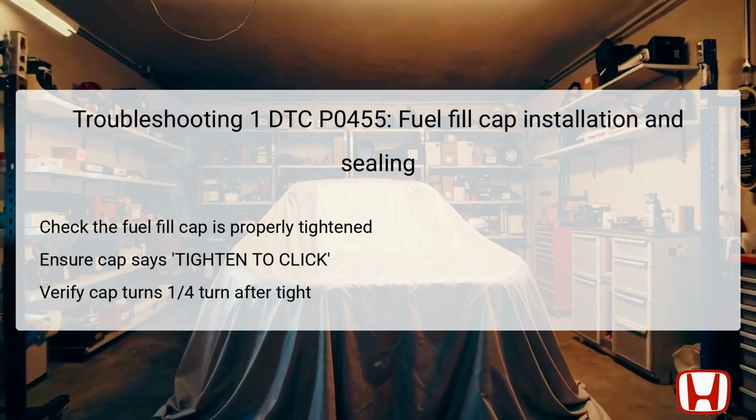A loose or improperly installed fill cap can cause the vehicle's diagnostic system to detect a large leak due to vapors escaping from the fuel system. If the cap is not tightened correctly or is damaged, replacing or properly tightening it can resolve the error. After correcting the cap, a repair verification should be performed to ensure the DTC clears, confirming the fix.